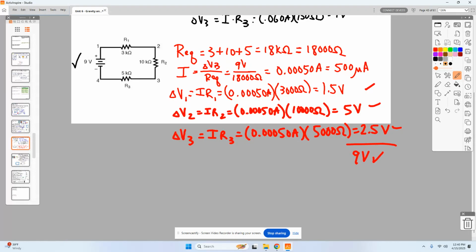And so again, no talking on that one, but hopefully you went through and were able to solve that problem on your own. Again, just pay attention to the kilo ohm, kilo meaning 1,000. And so when I go through to do these things, I would convert that 18 kilo ohms to 18,000 ohms, so that when I go through to determine the current and take that 9 volts divided by 18,000, I get 0.00050 amperes. That would be 500 microamps.